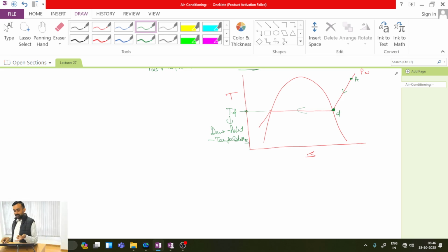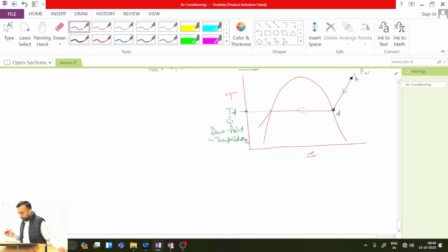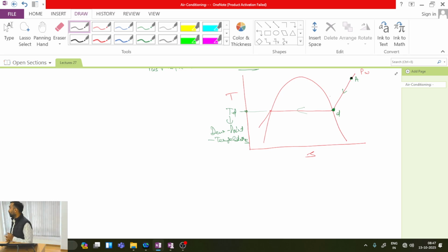However, what generally happens, which we also see whenever we cool in our split AC or window AC unit, is that because of cooling, some moisture forms and that goes out. Another interesting point is, whatever given mass of moist air I have at point A, instead of cooling it under constant pressure, if I cool it adiabatically, what is the meaning of adiabatic cooling of moist air? How can I do adiabatic cooling?